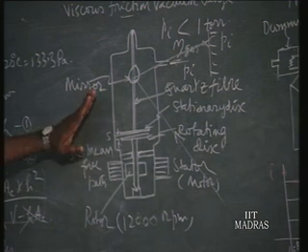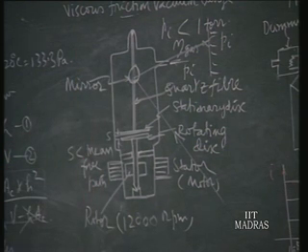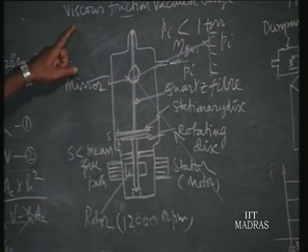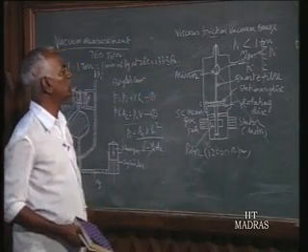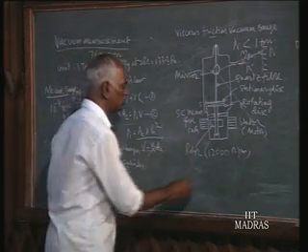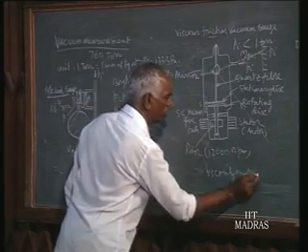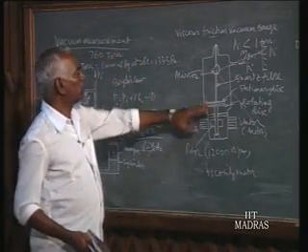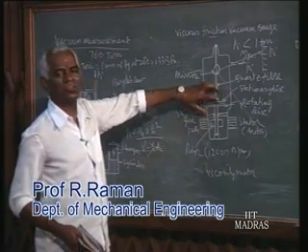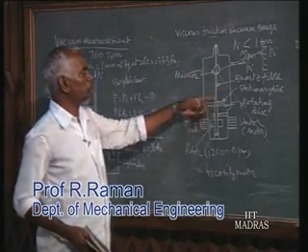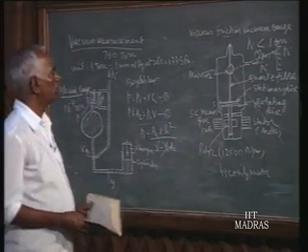Also this instrument is used in finding this principle: the viscosity is proportional to pressure, and the torque transmitted to the disc is proportional to viscosity. That principle is used in the viscosity meter also. For measuring viscosity of liquids, a similar arrangement is there. The rotating disc, the liquid kept at different temperatures, whatever torque transmitted is proportional to viscosity. That is the same principle used there, but here we are using that principle for vacuum measurement.